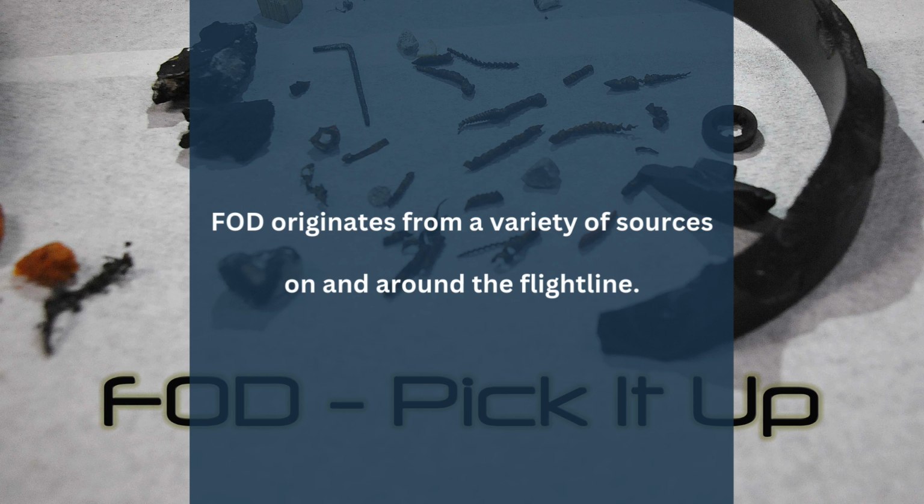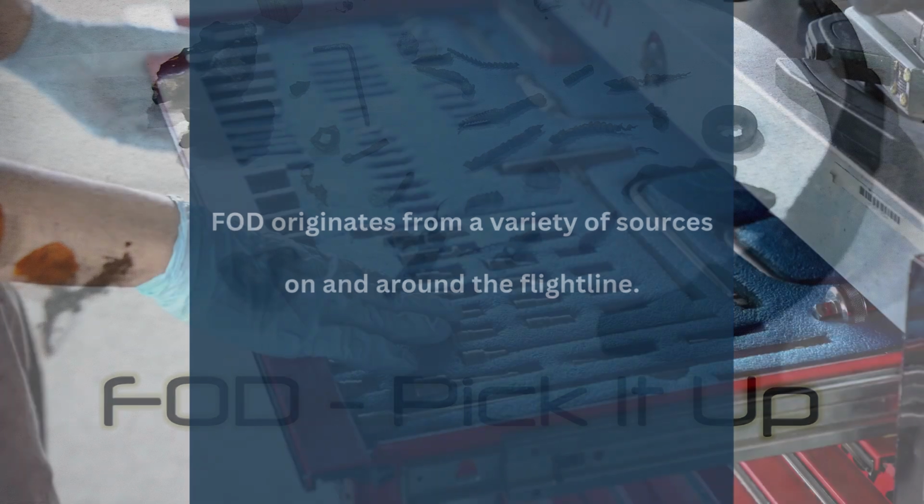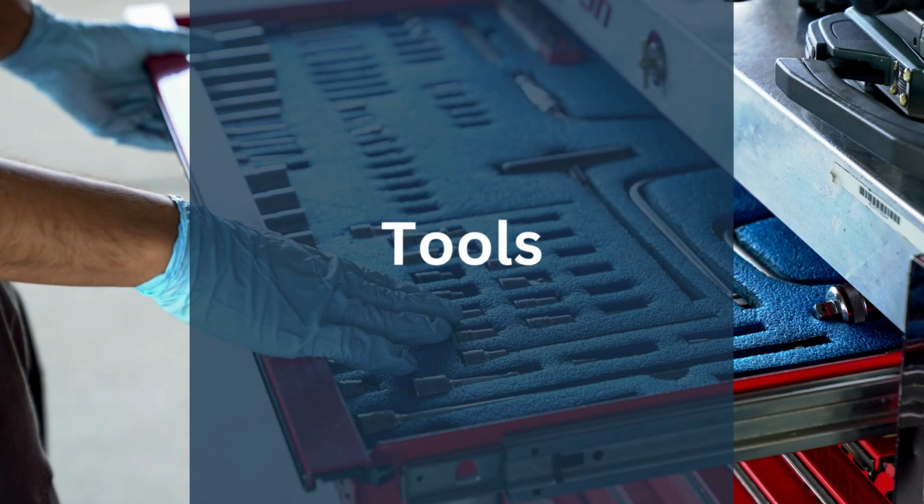Understanding these sources is crucial for effective prevention. Let's take a closer look at the most common sources of FOD and how they threaten aircraft safety. Lost or forgotten tools, like wrenches, screwdrivers, and sockets, can easily be left behind during maintenance. If ingested into an engine or caught in moving parts, they can cause catastrophic damage.